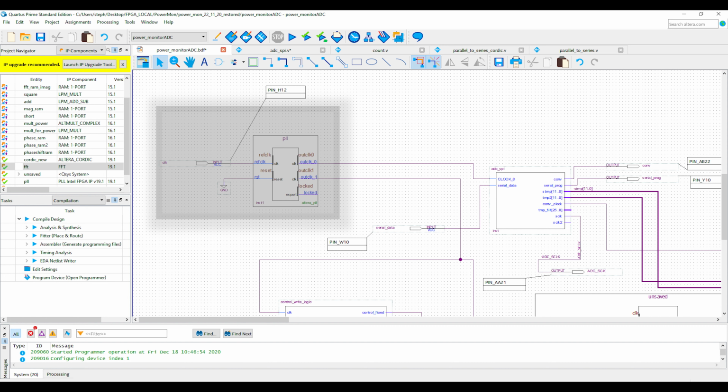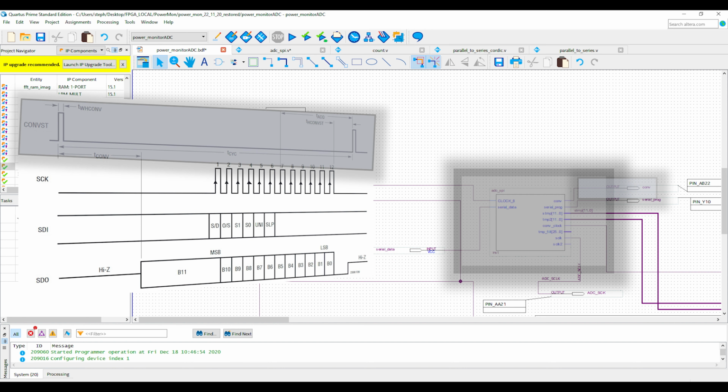And if we look at the timing diagram, we'll see that we have an input pin that carries the 12 bits of the sampled word, but because this is a serial A to D converter, they actually come in 1 bit at a time. This complicates our interface code because we actually have to pick off those bits 1 bit at a time to form the 12-bit word. We've also got this convert pin that initializes the conversion.